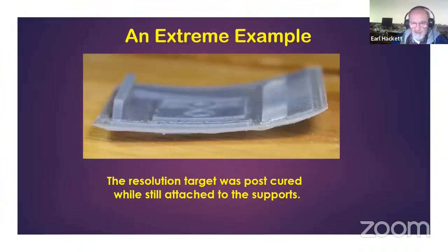Remember back when I started this, I talked about the resolution target. When I showed that to you, this thing was perfectly flat. And that's what it looks like today, 4 weeks later. What happened, when I put it in the post-cure unit, it was still attached to the base. So the top got a full dose of ultraviolet, cured it up good and solid, and then I cut it off the base. Well, the bottom, of course, was in shadow. It got very little.